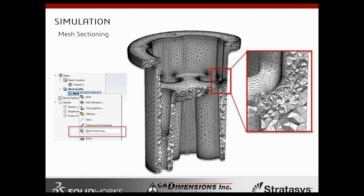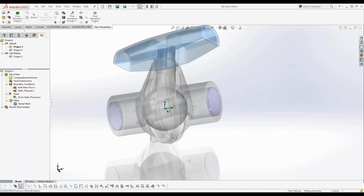To access this mesh sectioning, you would have to go under your mesh quality folder. You would create a mesh quality plot for that mesh, and then you would right click that mesh quality plot and select mesh sectioning, and that will give you the option to select a plane, actually probably not even a plane. Let's actually take a look at that.